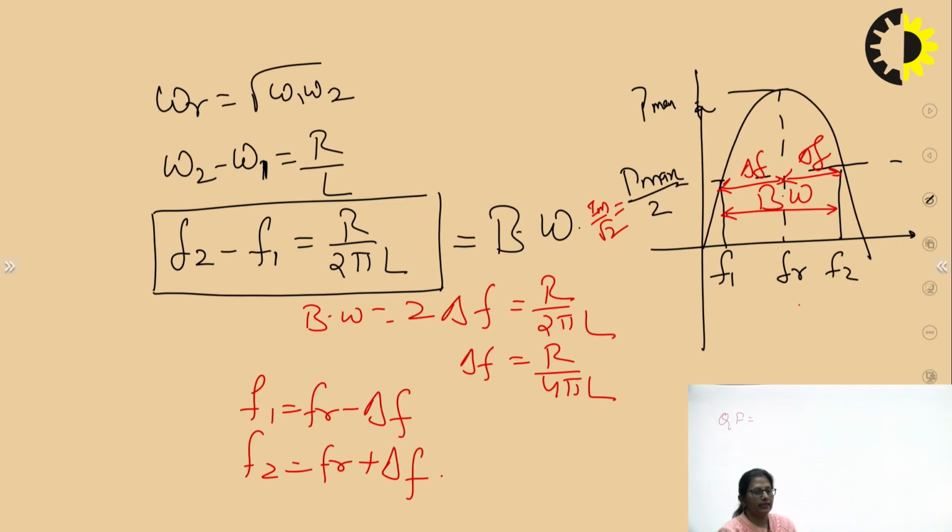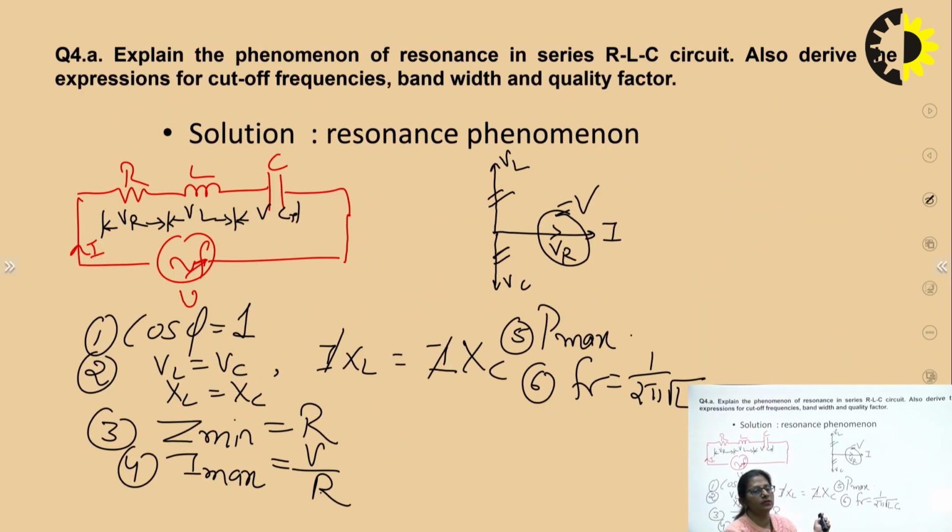Now, the quality factor for a series resonant circuit is given by the voltage magnification which is occurring in the circuit at resonance, right? So, if we just see in case of series resonant circuit, at the resonant state, the voltage across the inductor and capacitor are going to be maximized, they are going to be magnified many times compared to the supply voltage.